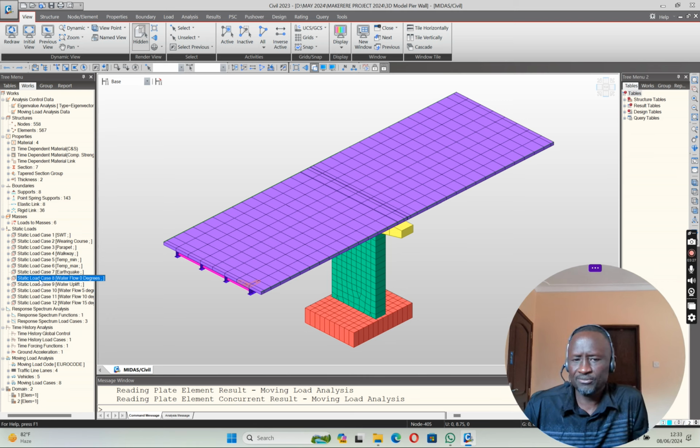That same factor, the formula that you use for wind or aerodynamics, is the same formula you use for water flowing across the pier support. The only thing is the density of air, now you change. You use the one of water.